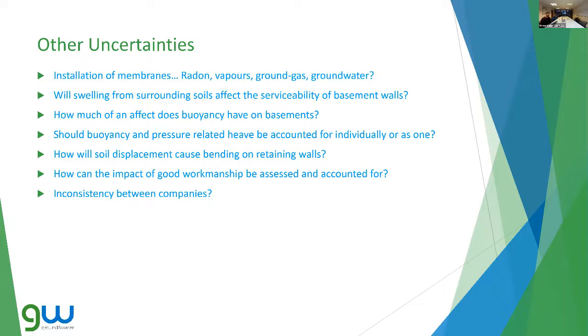Will swelling affect the serviceability of the basement walls? Will the heave below the basement slab from the overburden pressure release cause bending of these retaining walls?